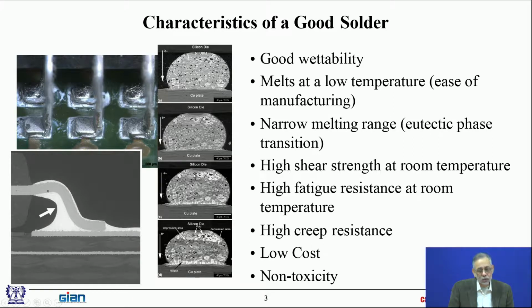So what does that mean? It's a 2-step process. One, it has to wet that surface adequately, and then it has to form a good intermetallic with that surface, right?